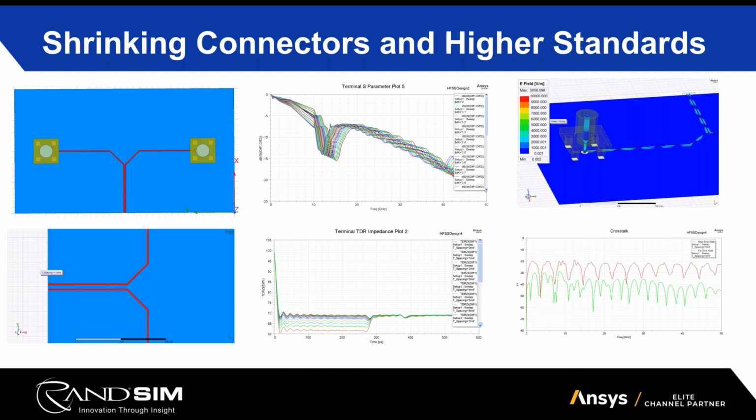Similarly, if you're not designing the connectors yourself, but purchasing them from a vendor, you're still going to want to do the simulation, but you don't have the connector. What you can do is get an encrypted model from the connector vendor. It's a hidden model of their connector to protect their intellectual property, but it's still going to allow you to fully simulate the connector as well as how it relates to the board.